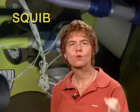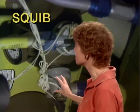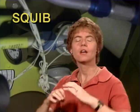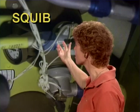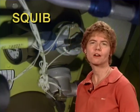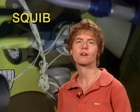Now, in a fire protection system like this, you have a squib, and the squib is the device that causes the fire extinguishing agent to be released. And basically, the squib is the explosive device that breaks open the exit way so that that fire extinguishing agent, which is under pressure, can push its way out and be released into whatever area you need to put the fire out in, whether it's the engine or some other area that's protected by this agent.